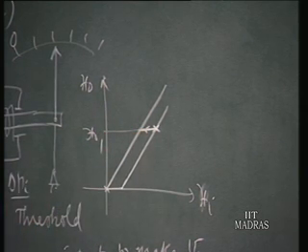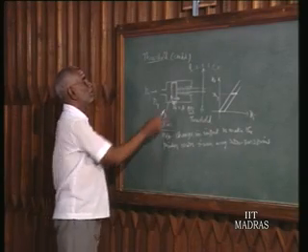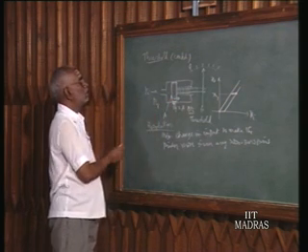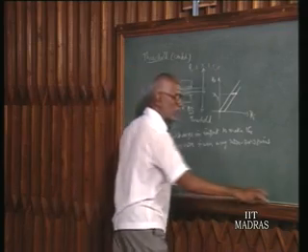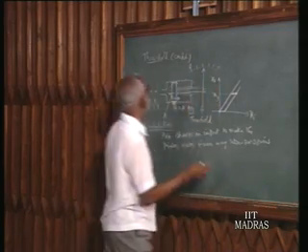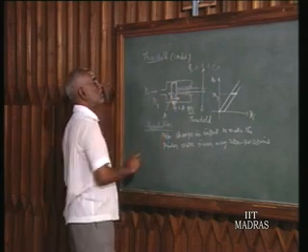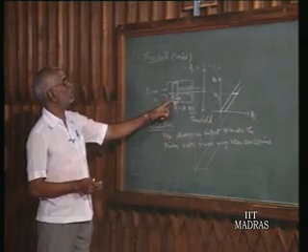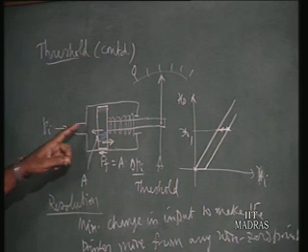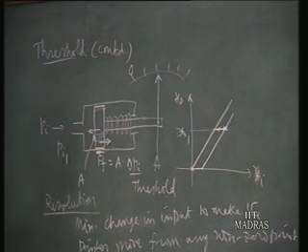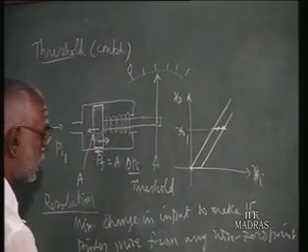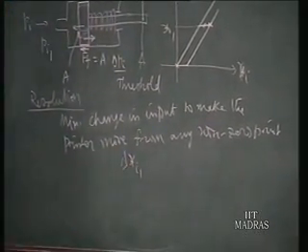In the same instrument, when the pressure drops from a certain Pi1 and the piston has to move backwards, again there is friction, acting in the opposite direction. Friction always acts opposite to the motion. To overcome this, there should be some drop in pressure Pi. Then only will the spring push it backward. So that much delta Xi is required. We will call it delta Xi 1.